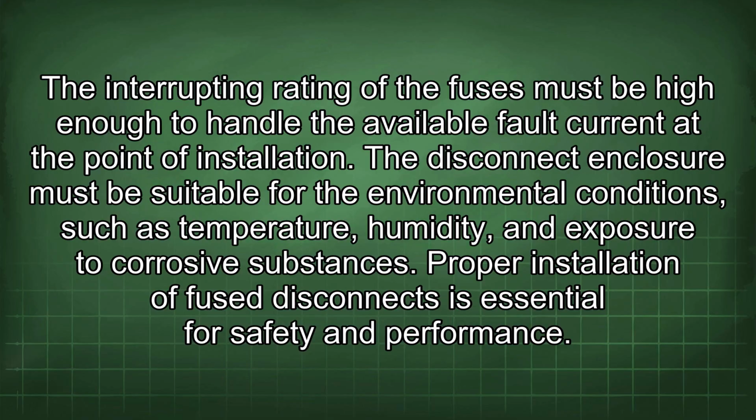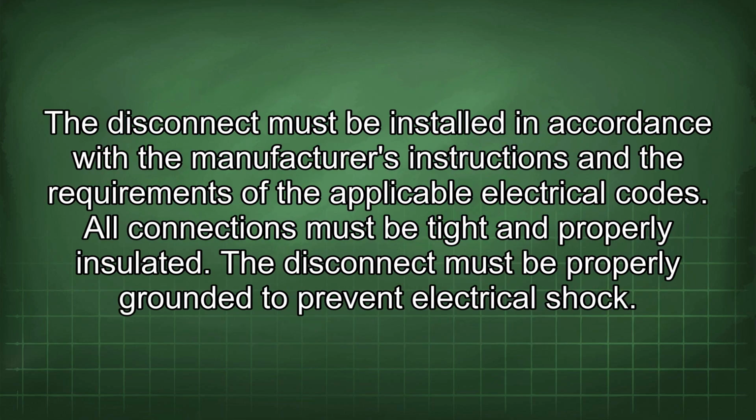Proper installation of fuse disconnects is essential for safety and performance. The disconnect must be installed in accordance with the manufacturer's instructions and the requirements of the applicable electrical codes. All connections must be tight and properly insulated. The disconnect must be properly grounded to prevent electrical shock.